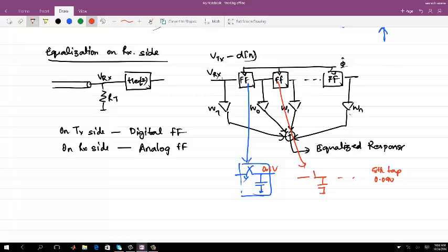The other thing is you are clocking. So if you use any switch to clock, you have a clock feed through coming in, which will be injecting charge into it, and the problem here is the signal which you are entertaining is actually a small swing signal. So if you disturb it, you do not know what's happening there. So it cannot be used for more taps. Maybe you can try with 1 or 2 if possible, but that needs to be very carefully designed.